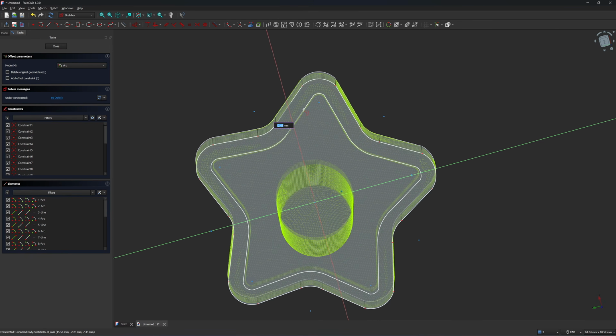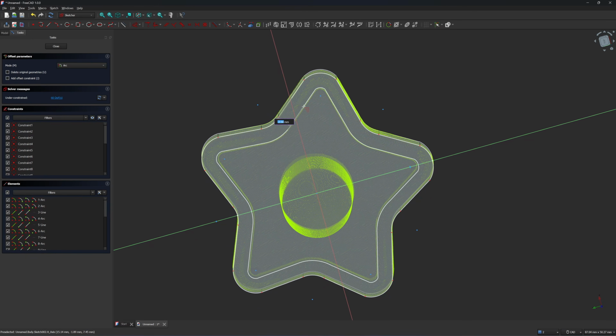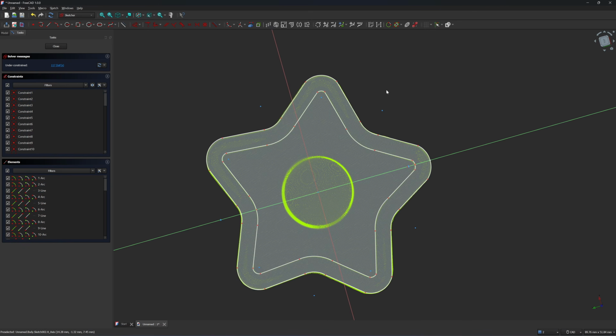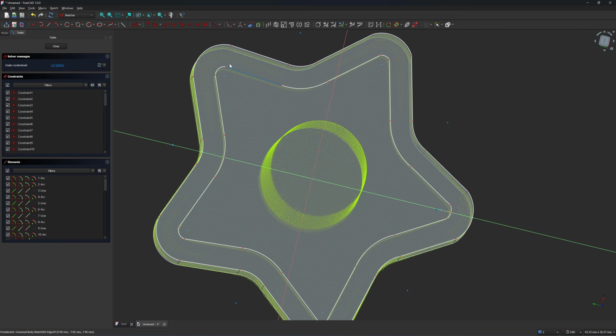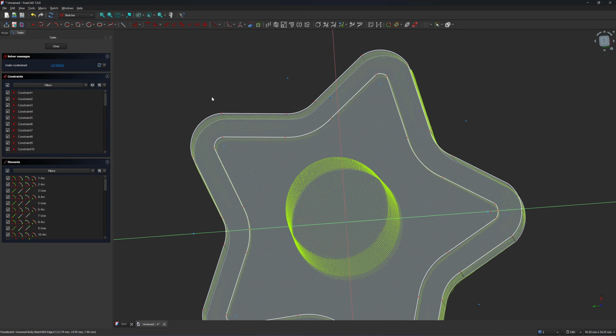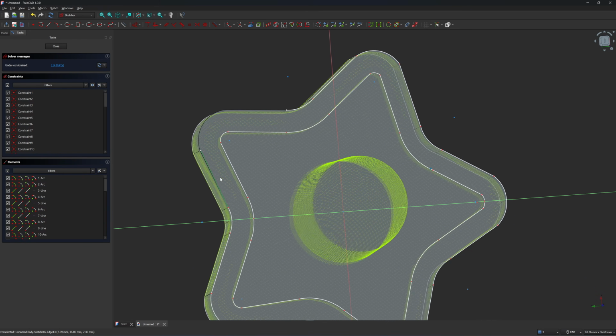And for FreeCAD, you need to input the offset number here, and you can't change it. I think it's 2.8, minus 2.8. Okay, and I'm going to use this offset line to cut the pocket. To do that, you need to delete this line, the first line that you just copied.